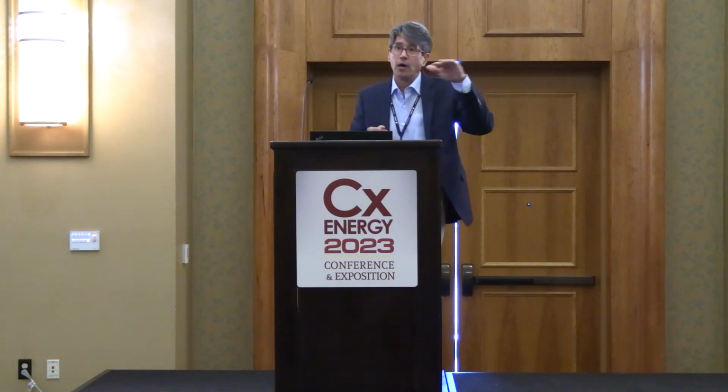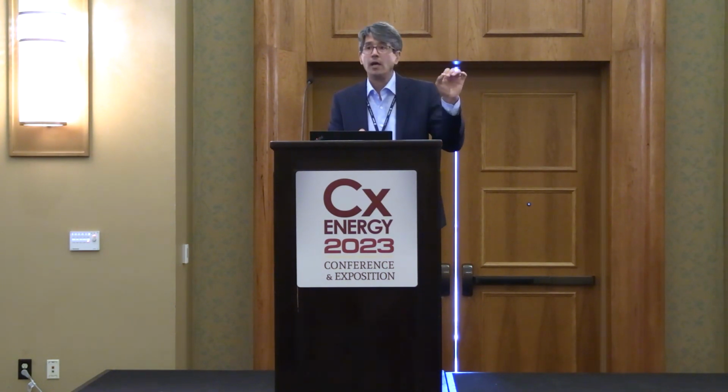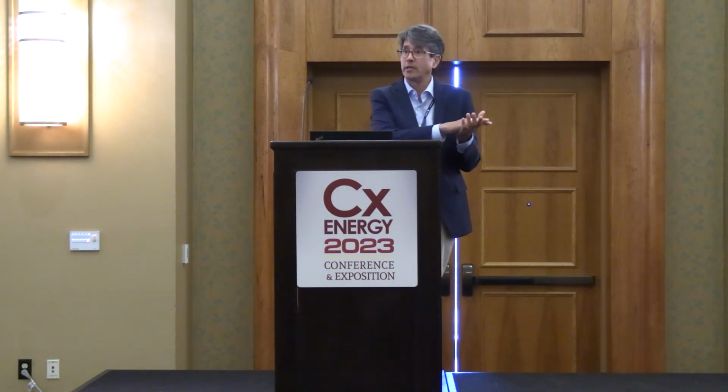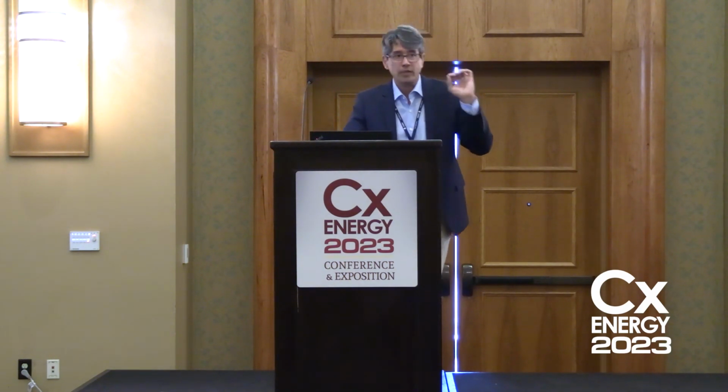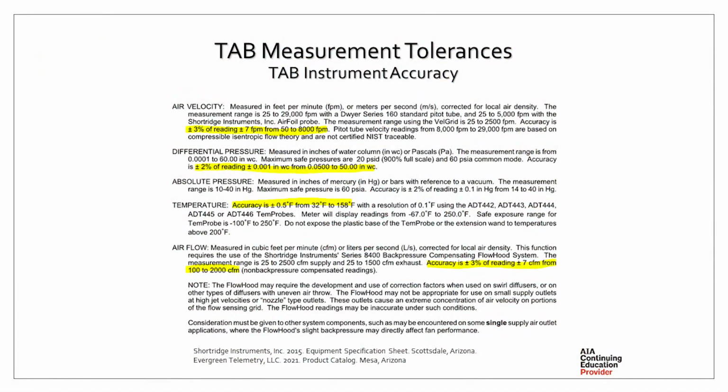So don't get hung up on thinking that I've got a critical environment that really needs to be controlled very well, that I need to balance this to plus or minus 5%. A lot of times your airflows aren't going to be in that range because we're trying to maintain a room pressure and air changes. So, one last thing, we'll go through design equipment selection. Once again, that could affect your TAB tolerances and what can be obtained. We'll talk about some balancing dampers, that kind of thing, in a minute.